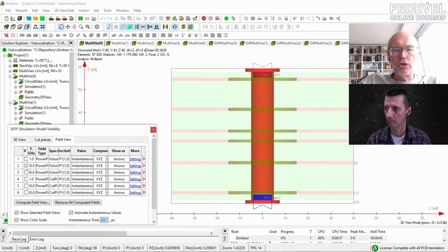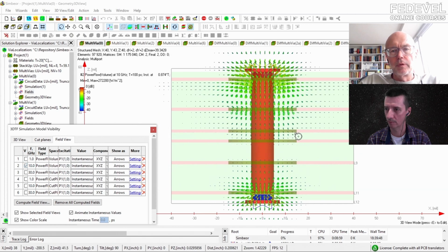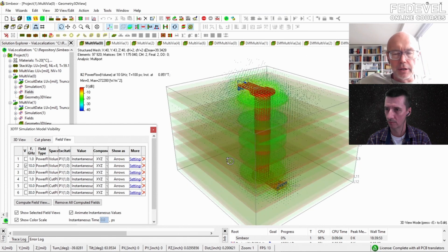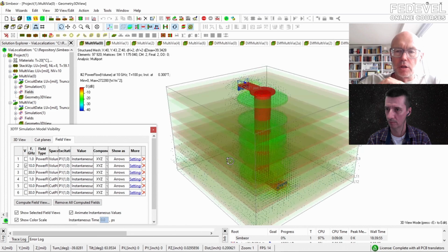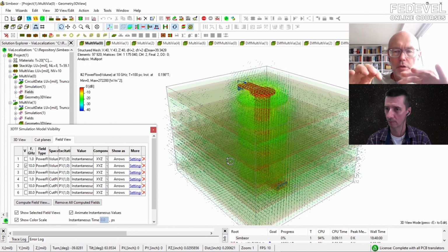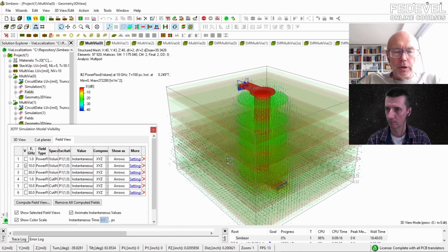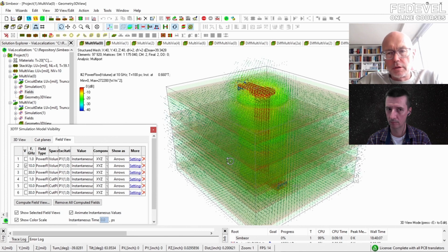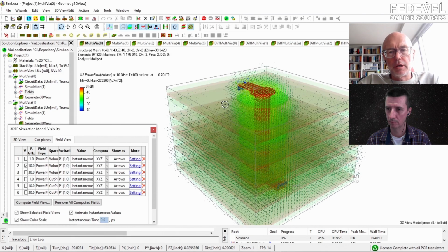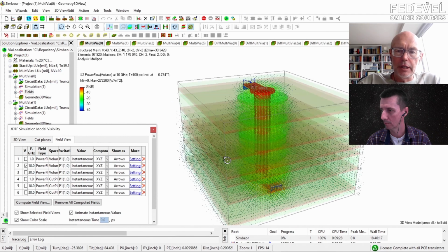What if you switch to 10 gigahertz? And you can see more energy spreading sideways. The boundary conditions here are infinite planes. So this is one of the specific Simbeor features where it can simulate planes that basically go to infinity. It's not a real board, which is limited in size, but it allows you to characterize how much energy you lose in the structure and possibly gain someplace else.